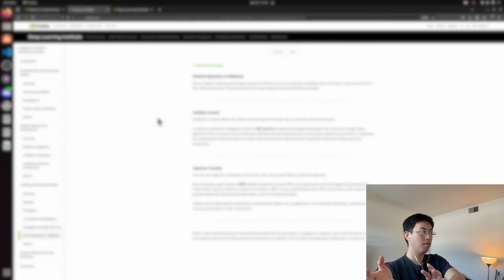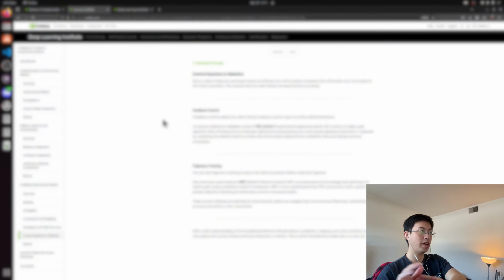Then we covered a little bit on the control system. The standard feedback control is what we call the PID, proportional integral derivative controller. It's very good at putting your robot into a position, rotating a robot, or controlling a motor at a very precise speed. And then for trajectory tracking, you have something called MPC, Model Predictive Control. It is a little bit more sophisticated than PID control. I don't remember a whole lot about MPC, but it comes with predictive behavior to understand your robot's path or to optimize your robot's path as it navigates.